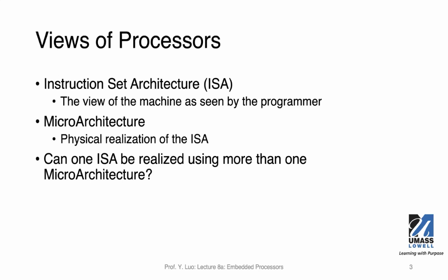So the microarchitecture defines, for example, do you use out-of-order execution? Do you do branch prediction? These types of things are more related to performance improvement of a particular design or power consumption optimization, but it will not change the instruction set architecture. So it will not affect the programs that you write in assembly language.